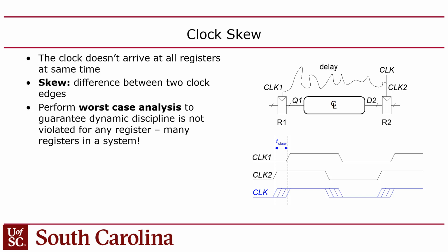So you have to factor the clock skew into the setup and hold time constraints. The reason for that is, for the setup time, what may end up happening is that the source flip-flops may have a clock signal that looks late compared to the destination flip-flops, meaning that the signals coming out of the source part, the inputs, may be running late relative to the destination, right? So that makes it look like there's more delay than there actually is, because they're getting a late start, right?